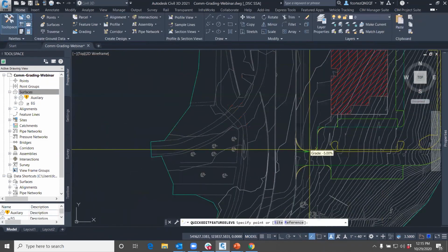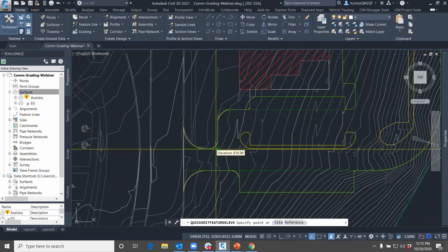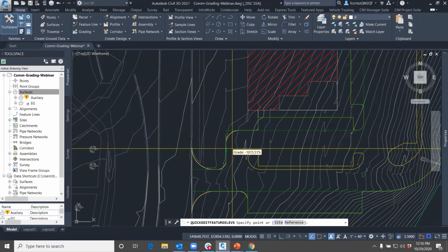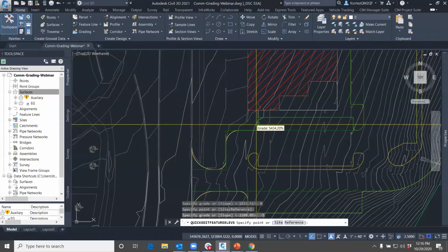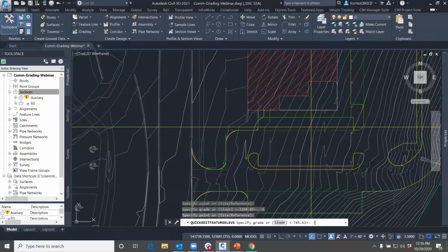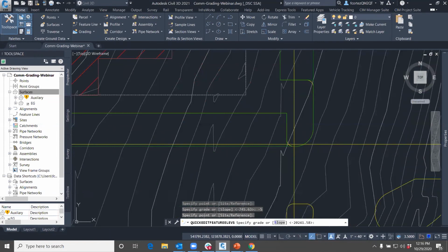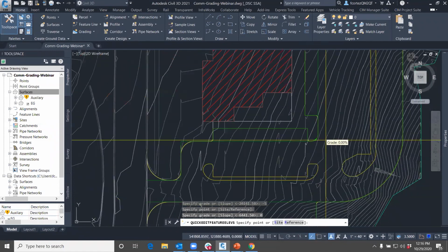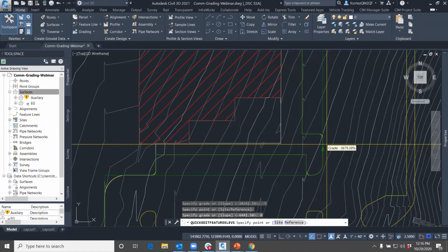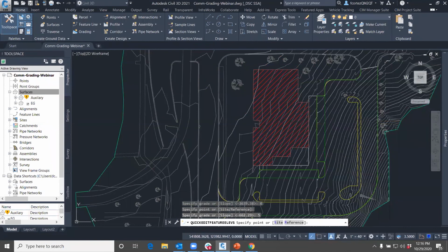And now let's finish coming along the front of the building. So we know that the water is going to come here and it's ultimately going to come down to this corner based on the existing ground contours. So we can go ahead and keep this flat, maybe come down at another 5%, maybe continue down at 5% in front of the building. And now we could probably keep this flat since it's going to be way higher than anything on this side. Keep that at 0. And now we probably want to start coming up at 5% on this side.